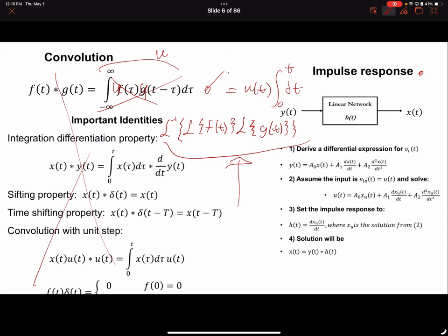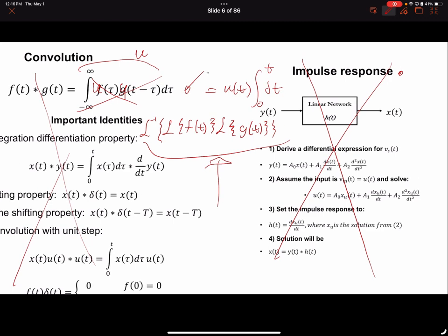Later on in class, though, we also learned a better method of doing this, which is to solve the circuit in the Laplace domain, assuming that your input is a delta function. And in the Laplace domain, a delta function becomes a 1-volt source. And so it becomes very easy, and you can assume zero initial conditions. You just need to know one of them, because to find your impulse response, you can use either one of them. Questions, concerns? All right.